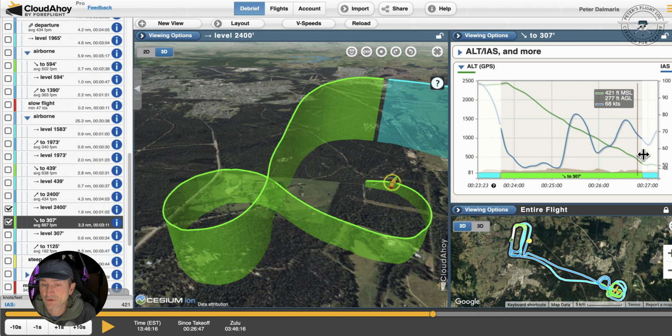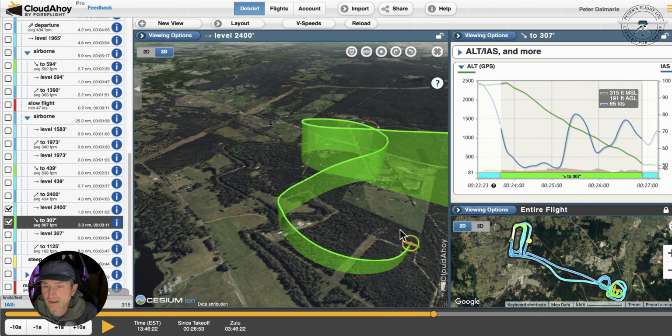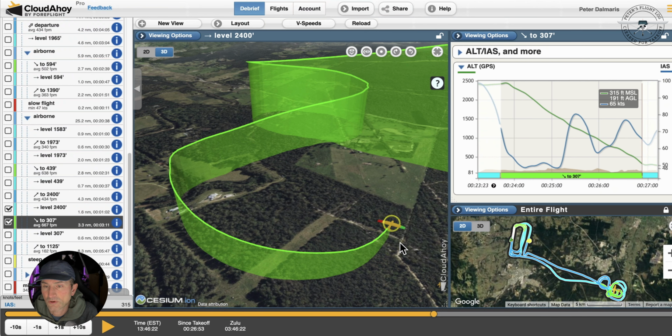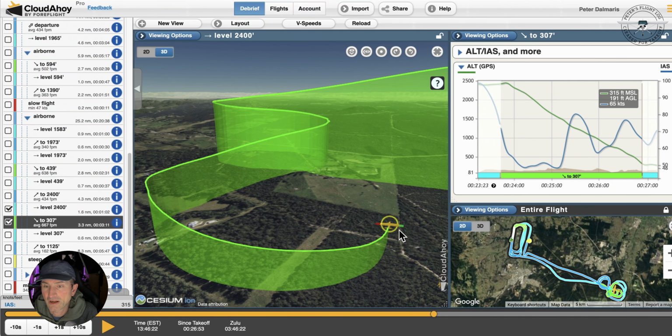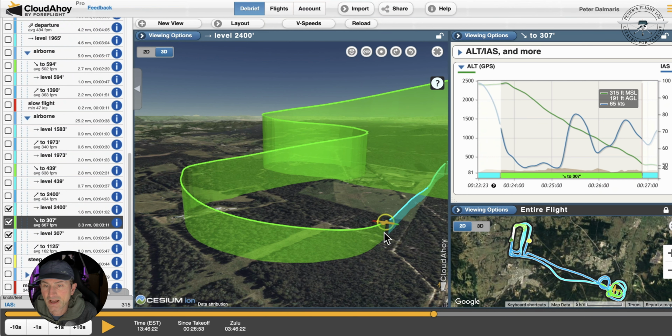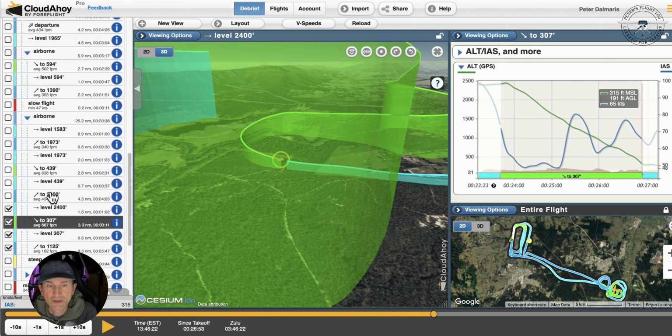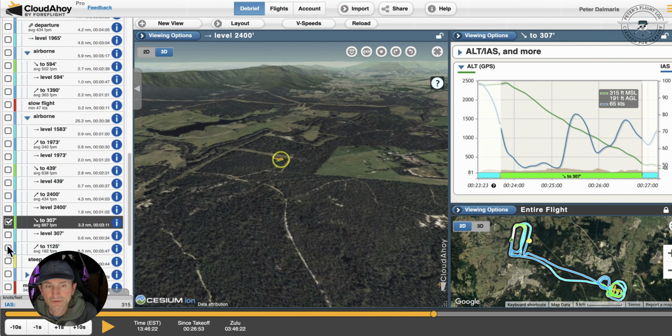At that point, I'll have also deployed flaps, and I can control my speed, especially overspeed, and eventually get to a satisfactory position. And I can be quite certain that at this point, I'll be able to make my chosen landing field, and I can just apply full power and climb again, which is what happens here. So that was the main thing that I worked on.